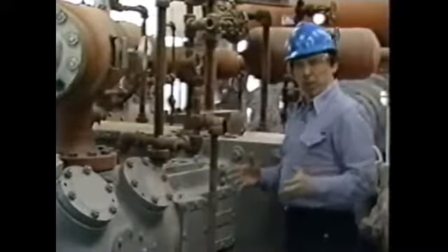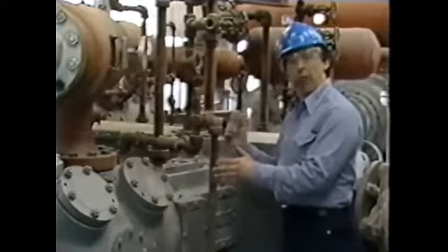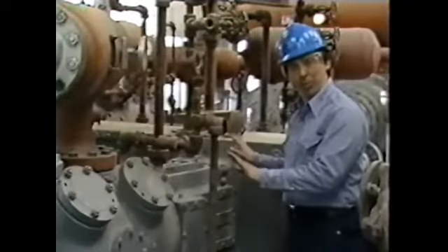In the cylinder wall is a lubrication inlet. Lubricant or oil forced through the inlet is spread over the length of the cylinder by the piston rings during the stroke. At the same time, lubricant is also force-fed to the packing on the piston rod. For some reciprocating compressors, the compression unit and drive unit lubricants must be kept separate.